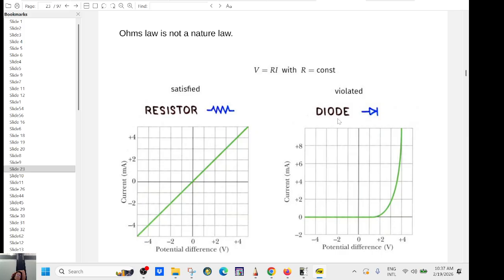That's why you always want to protect a diode with a resistor, because otherwise it's out of control. When you are working in electronics, you have to use the datasheet that goes with it, which describes how the current will respond to the voltage, right?